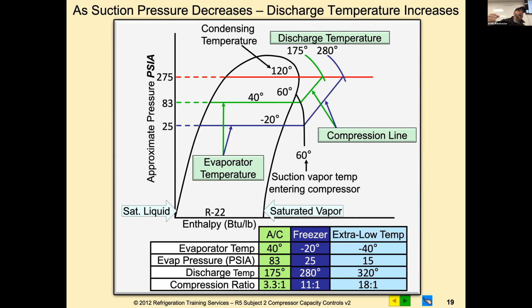So even though the discharge line is hot, that refrigerant is still trying to pick up any heat it can. We don't start to desuperheat until we hit that condenser. All the way through the evaporator and through the heat of compression at the compressor, up until it hits the condenser, it's trying to still absorb. At that point, when it starts to cool under pressure, it starts to give off its heat instead of absorbing.